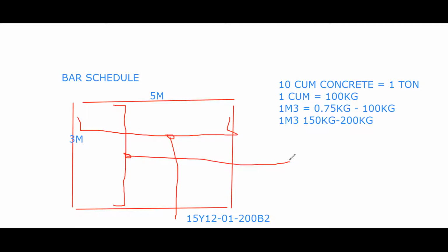I've done a bill for a client in 24 hours for a 4-story building in 2016. I'm not bluffing. The client himself, the consultant, was surprised. How did he come up with a bill for a 4-story building, the concrete work only, concrete carcass, in 24 hours? Yes, I did it. Because as soon as I computed my floor, number of columns, each column, how much concrete will it carry? I multiplied by the number of columns, and my cubic meter for all the columns came out.